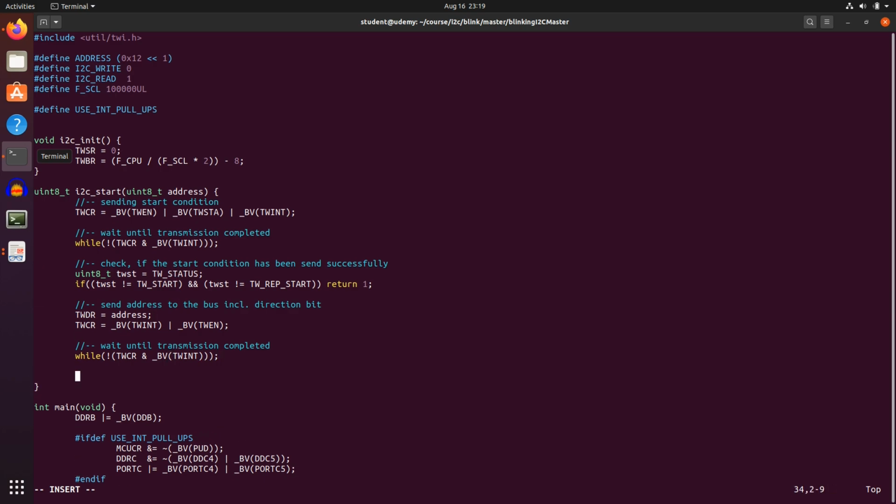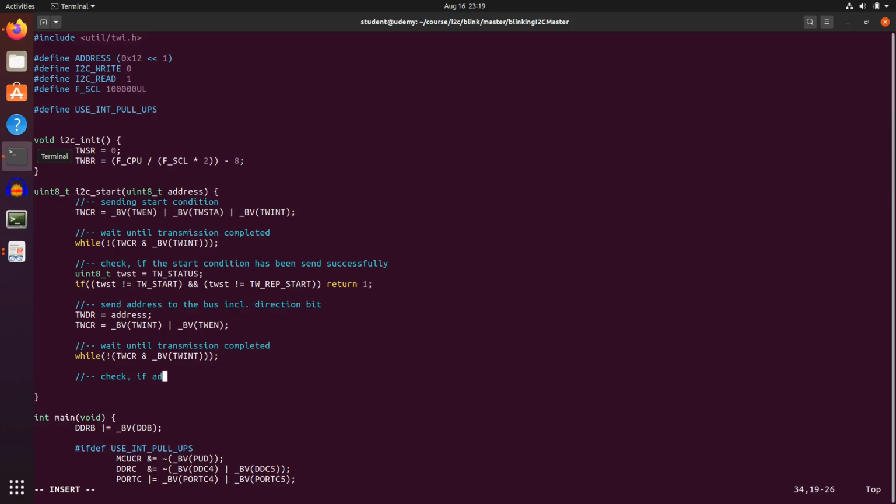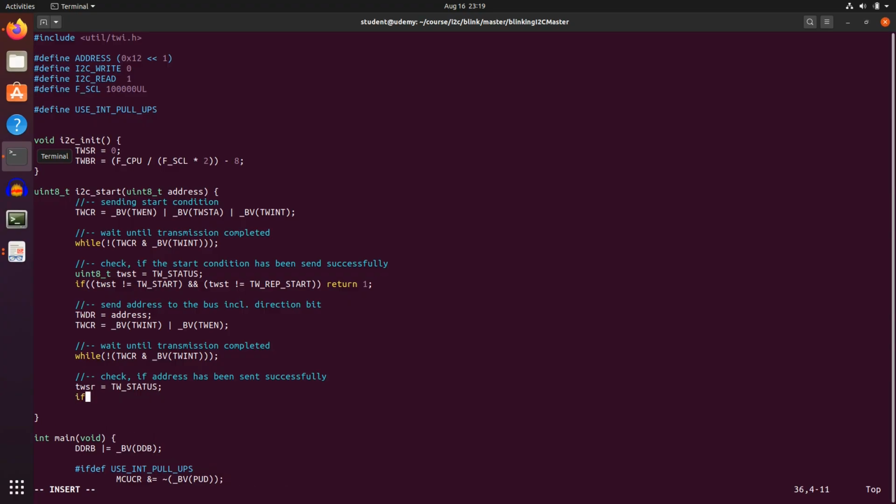I can wait till this has been sent, and then I check if the address has been sent. So again, check if address has been sent successfully. TWSR, TW_STATUS, now I'm expecting the status register. Oh, sorry, it's TW_STATUS.